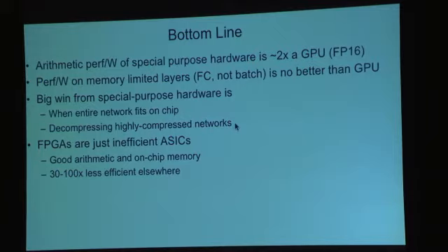If we're representing the weights by 4 bits, there's bit manipulation to extract the 4 bits you want, a table lookup to look up the code word and decompress the code word. That stuff runs really well on special purpose hardware and not so well on CPUs and GPUs. So there's a big win for the special purpose memory system for the decompression, not so much for straight arithmetic. GPUs are within about a factor of 2 on FP16 for the straight arithmetic.